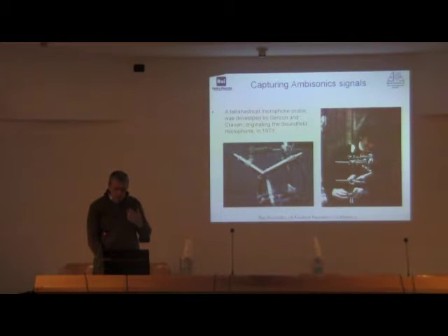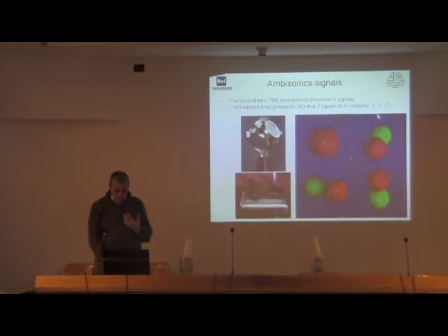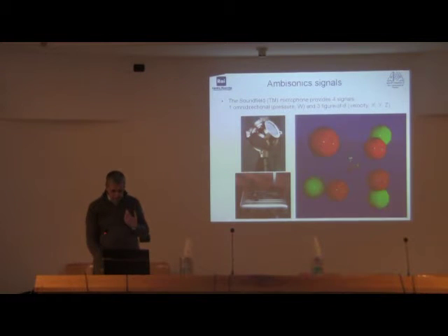This is the very old origin of ambisonics, due to Michael Gerzon and Peter Craven in the 70s. And here you see the very first prototype of the sound field microphone, and this is our current one. The ambisonic theory is based on analysis of the sound field, which requires only 4 channels for describing it completely, which are pressure and the 3 Cartesian components of particle velocity. And the sound field microphone delivers these signals by an analog processing box, which is this small black box here.